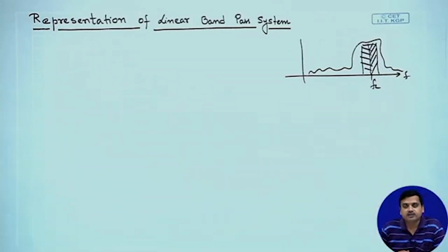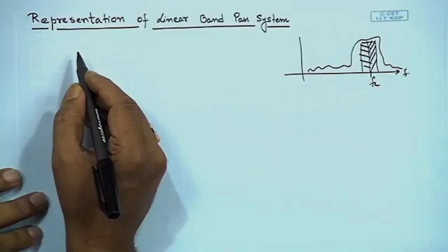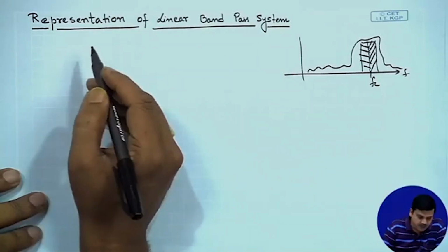Generally, we send signals in this form. So, since the signal is going through the pass band, or in other words, we have the pass band signal and we are bringing it down to its low pass equivalent representation, if we have to analyze a system, we should also find the equivalent representation of the channel in its low pass equivalent form. So, let us consider a channel which is a band pass channel.